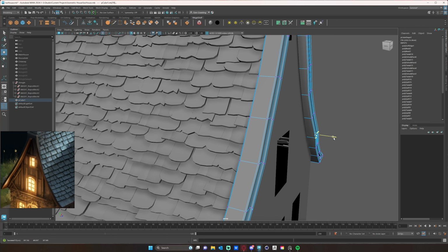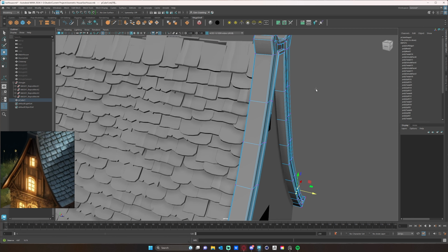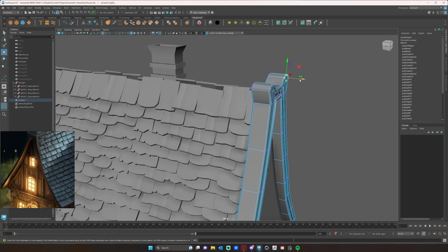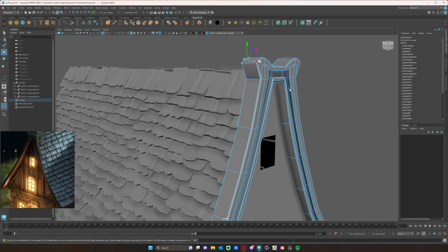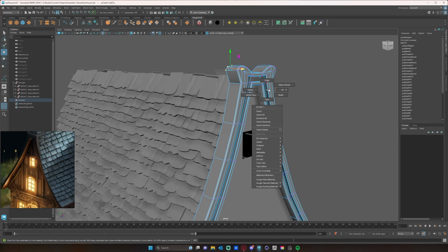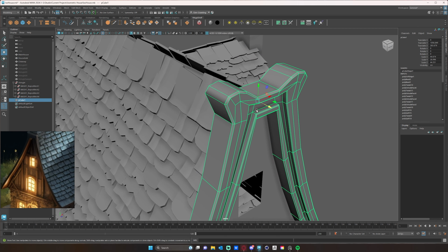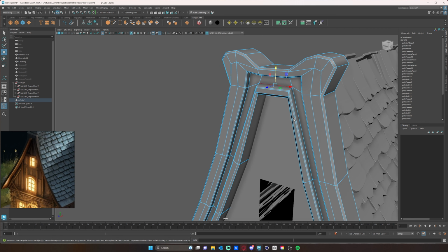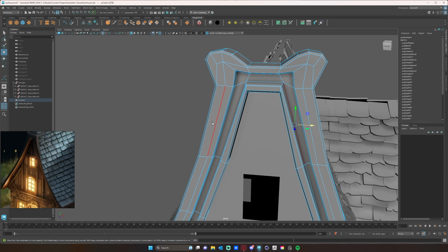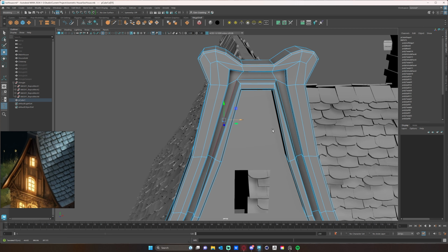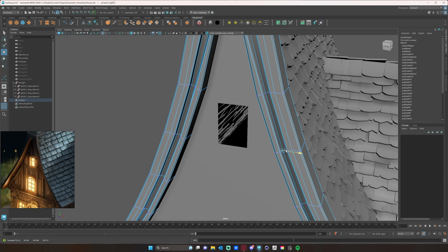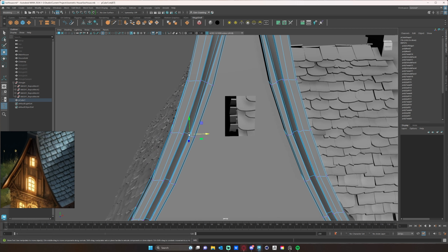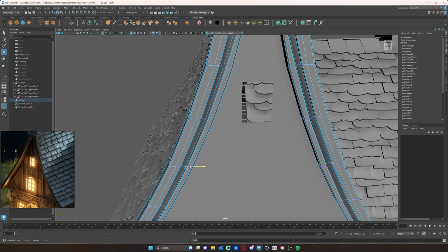The one thing I like to say is there's no straight lines in real life. So if you can make things a little bit asymmetrical, roughen things up a tad bit, even if it's a very new straight looking model or building. It's very rare that anything has perfectly straight lines in real life. And unfortunately, that's one thing that 3D does very well, is makes everything look nice and organized and have straight lines. So we need to manually go in and mess things up a little bit if that's the case.